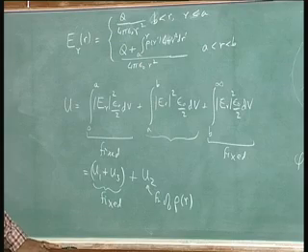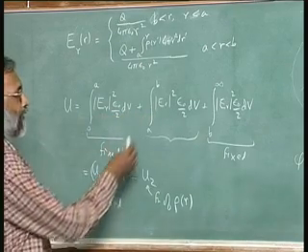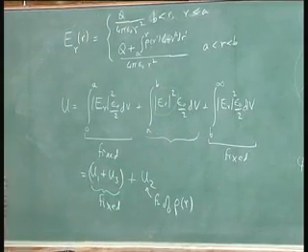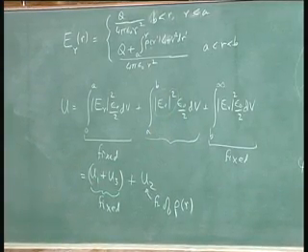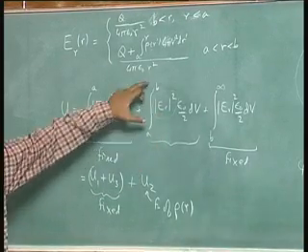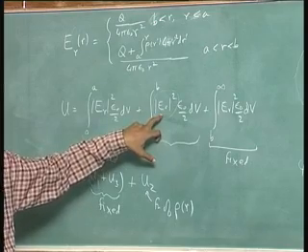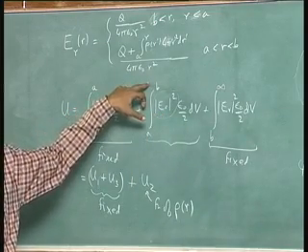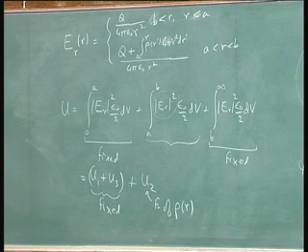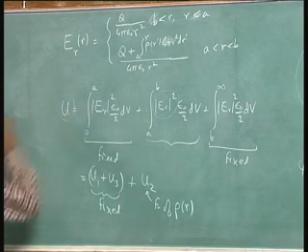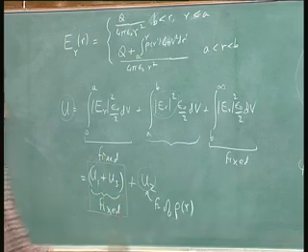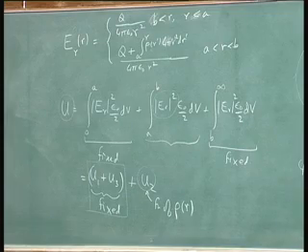The second thing that is very obvious from this integral is that I am talking about something that is always positive or at worst 0. E squared cannot be negative. So, when I take the integral of something that is either positive or 0, the integral is always positive or, worst case, 0. So, I have that the total stored energy is equal to some fixed part plus one more part that is either 0 or greater than 0.